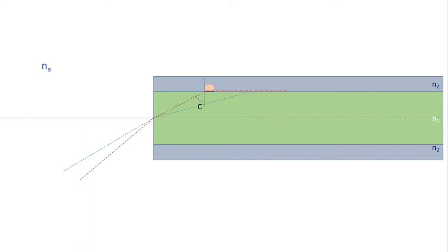Light entering will be striking the core cladding interface at an angle greater than the critical angle. Hence, it undergoes total internal reflection. This light undergoes multiple total internal reflections and can make it to the other end of the fiber and is usable for communication. Let us consider another pathway beyond the reference path as shown.